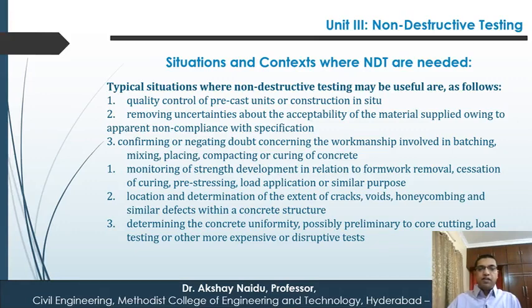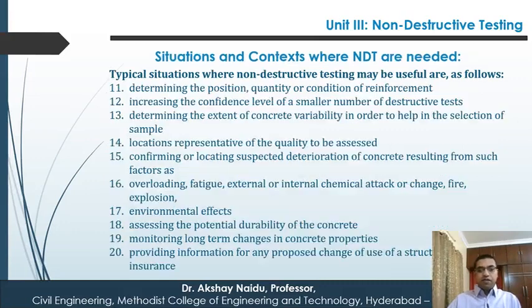This should be 4, 5, 6. Monitoring of strength development in relation to formwork removal, cessation of curing, pre-stressing, load application or similar purpose. Location and determination of the extent of cracks, voids, honeycombing and similar defects within a concrete structure. Determining the concrete uniformity, possibly preliminary to core cutting, load testing and other more expensive or disruptive tests. So many.